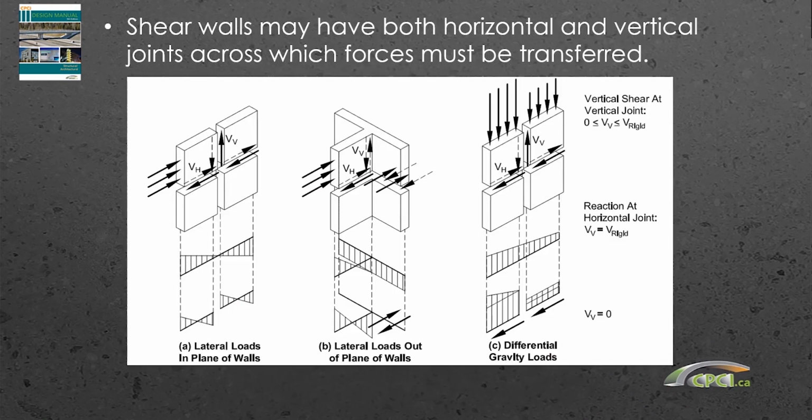And again, just a quick tip when you're designing shear walls, we're creating them not as monolithic cast-in-place walls, but as wall segments tied together, either vertically or both vertically and horizontally. And you have to design the connections between all of your different shear wall elements. If you're transferring load around corners or vertically from panel to panel, you need to properly account for all the shear and moment transfer between all the individual panels to get the structural behavior that your analysis is based on.